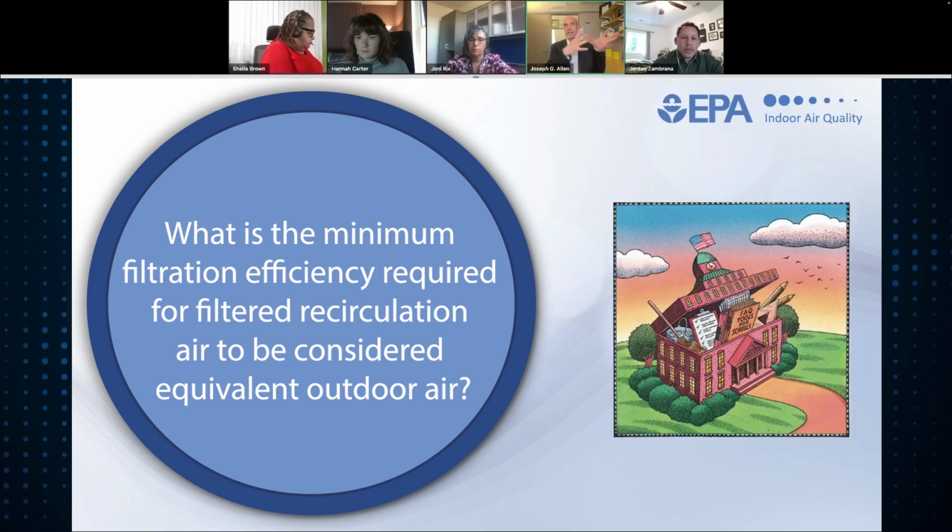The theory is, hey, we don't need outdoor air if we just clean the indoor air and make it as clean as possible. It assumes we know exactly what to clean. It assumes we can effectively clean it. And it ignores, honestly, a lot of the scientific evidence that shows benefits associated with higher outdoor air ventilation rates, inclusive of everything that means. So I'm hesitant. I wouldn't go one or the other all the way. I think it's a combination of good ventilation and good filtration pickups, especially when outdoor temps are extreme and you're going to have to close the outdoor dampers a lot, but not all the way.